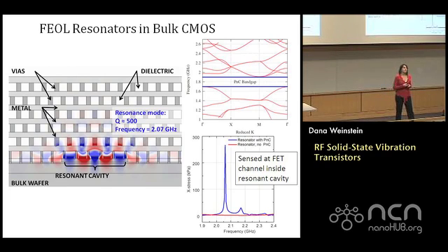So we can find these modes in these more complicated structures, which involve maybe several metal layers, leveraging both vias above the structure as well as vias on the side, and the transistors for driving and sensing are all in here in the middle, in the resonant cavity. And we can get high quality factor, high amplitude vibrations resonators.